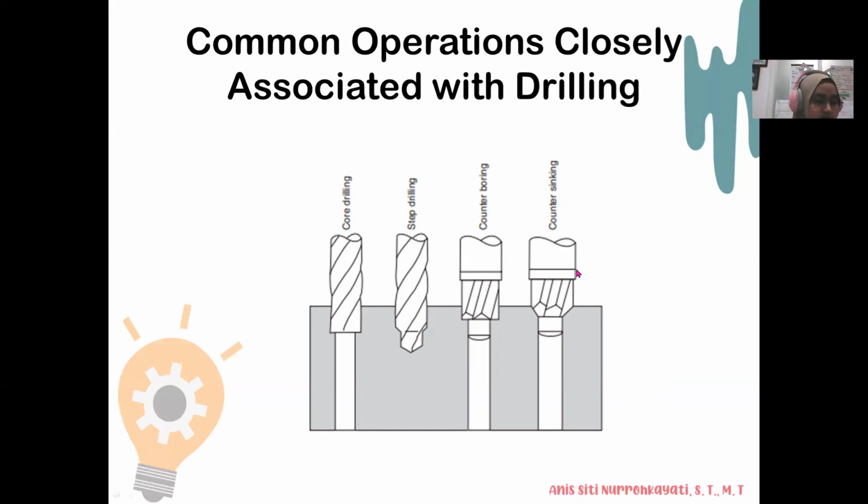Then countersinking. Countersinking provides a tap entrance to the hole. A special countersinking tool with a pilot is used, as shown in this figure. These are the common or basic operations that we can perform on drilling machines.